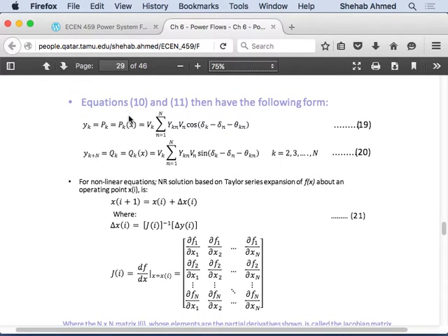And we said that the P of x and the Q of x are the power flow equations that we know at a specific bus. So the P of x and Q of x are these summations that we have, the power flow equations, at every bus. So these are my knowns. Pk is the real power known at that specific bus, Qk is the reactive power known at that specific bus, and it is equal to that right-hand side, right? So that's the equation.